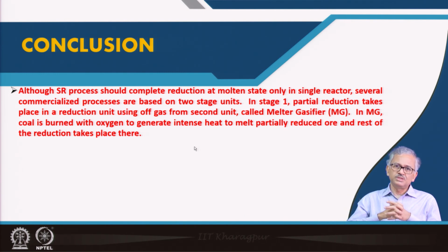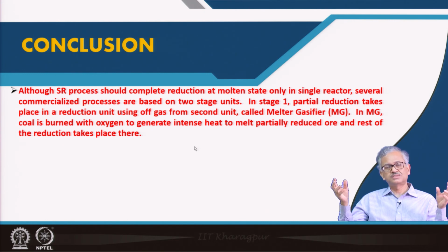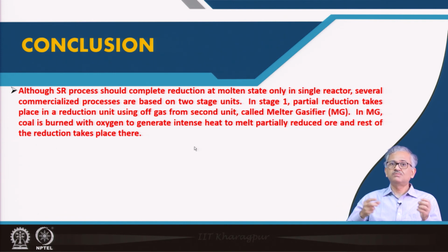So the only difference between the two processes is that in the Acer process you can use very low grade raw material like coal, non-coking coal, and low grade iron ore fines. So any kind of ore fines, ultra ore fines, and then you can utilize the iron bearing solid waste from the plant. So all these low grade raw materials you can use in the Acer vessel, but you can get a similar quality of hot metal to that of the blast furnace. Only thing is that the reactor is designed in such a way that it does not have much complexity of the blast furnace.